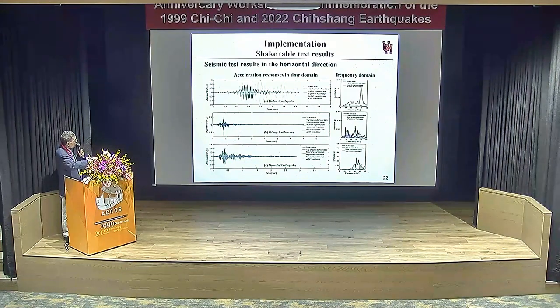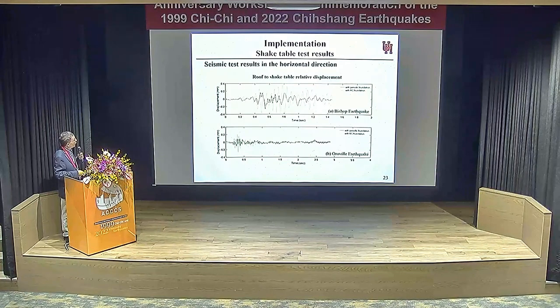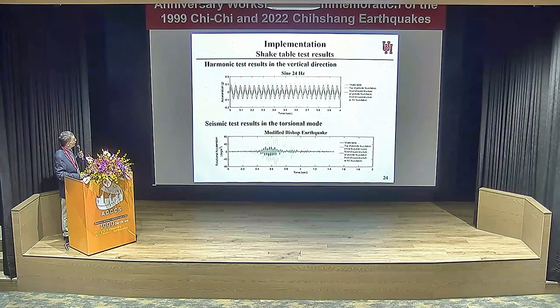Gilroy, and Oroville. When we transform the time history to frequency domain, as you can see, the pink curve, the amplitude become very small, very small. We know metamaterial foundation isolates all the incoming waves for all these 3 seismograms. And this shows the displacement comparison with the RC foundation and metamaterial foundations. Continue, we also did this harmonic test. This shows the comparisons.